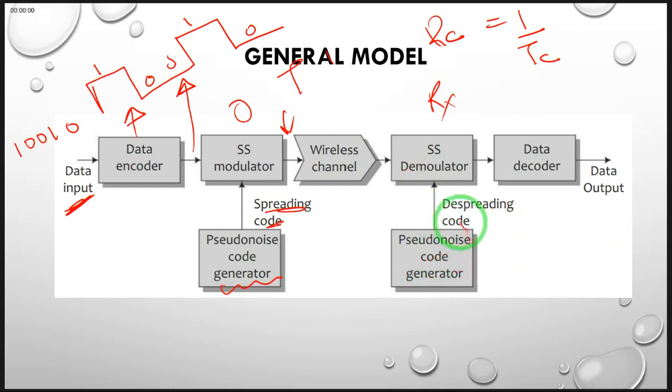When we apply this spreading code, the interference is spread, and therefore its effect is reduced or minimized, and we are able to recover our data pulses. This is the kind of signal that we receive at this stage, and the data decoder generates for us our binary data stream, in the form of zeros and ones.